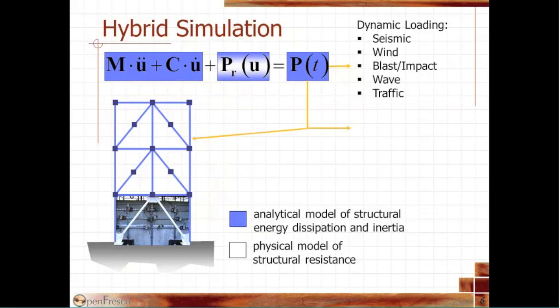Other loads that we can put on are static loads. So before we actually run the dynamic analysis, we can put on static loads. So we can put on gravity loads, or if we like, pre-stress loads. And this is important. I will show you in the example later in today's presentation how this becomes important and how we can do that.